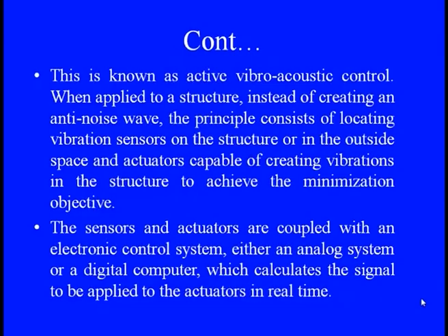The spring is a perfect storage device, but if we want to effectively control the vibration exactly at the source, then this active concept of the vibration, in which you see the force is being superimposed on that, is a perfect solution as compared to the passive one. So, sometimes we are saying that this is the active vibroacoustic control, because through that we have not only the control on the vibration feature of the system, but also whatever the spreading part of the acoustic level is there, that can also be controlled at the source.